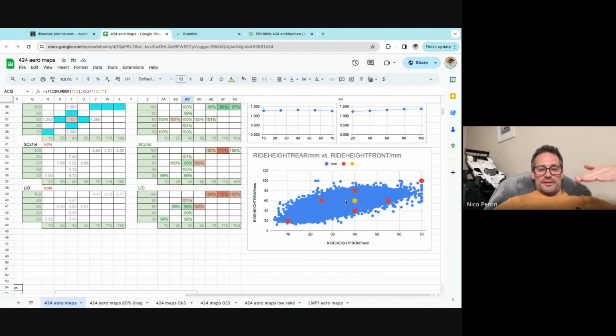So you see how the car goes up and down, and there is a spread because there is a bit of pitch movement as well. But you can see that the map is fairly well centered. So our main point of testing is 4060, right in the middle of that cloud of points. And then the spread of the map as well. You can see why the testing points in CFD have been chosen this way, just to cover that sort of cloud of points. This is a nice way to look at it and check that we're testing at the right attitudes.